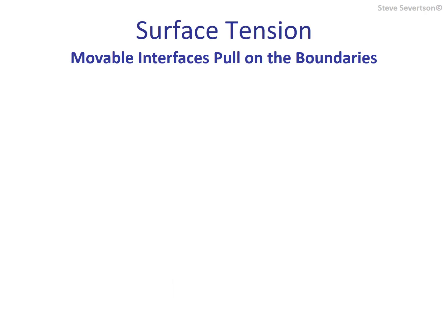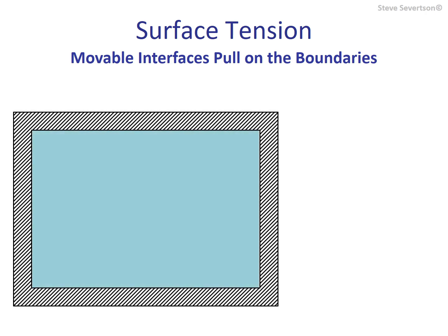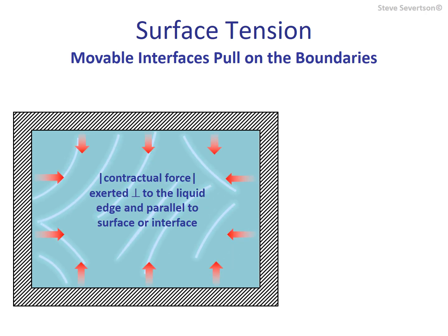At this point, we will pivot slightly to address the topic of surface or interfacial tension. Surface tension and surface free energy are essentially describing the same phenomenon, precisely the tendency of surfaces to contract to reduce their size spontaneously. From a mechanical perspective, we can think of the surface as a thin skin or membrane that separates adjacent homogeneous phases. Its contraction manifests as a force that acts perpendicular to its boundaries and parallel to the surface plane. We define surface tension as the magnitude of the force per unit length of the boundary.